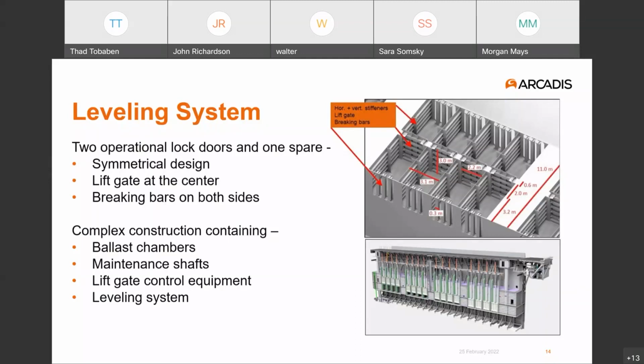In the lower figure, you see kind of a vertical slice cut through one of the doors. And as you move from the left to the right in the image, you'll see near the bottom of that cutaway 16 openings. And those would be the openings through which the water goes, and the sluice gates that control the flows are located at different positions. So on the left, 4 of the openings are completely open, and then as we move to the right, in various degrees, the sluice gates are being dropped. So it was quite an interesting piece of engineering overall.